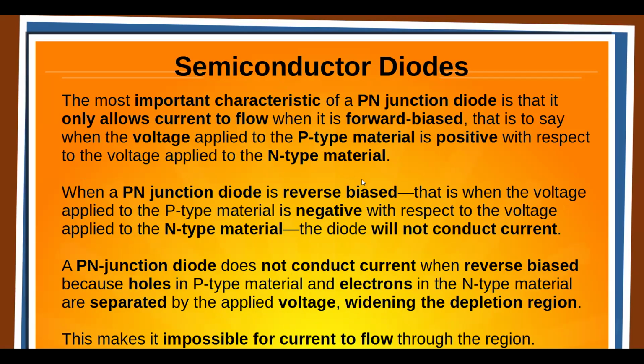For a general purpose diode, it's just a p-n junction, nothing special about it. You have to forward bias it, in other words, overcome that barrier voltage in order for it to conduct. And it only conducts in the forward direction normally. If you apply a reverse voltage at a certain point, it will avalanche and conduct in the reverse direction. It's called the Zener effect.